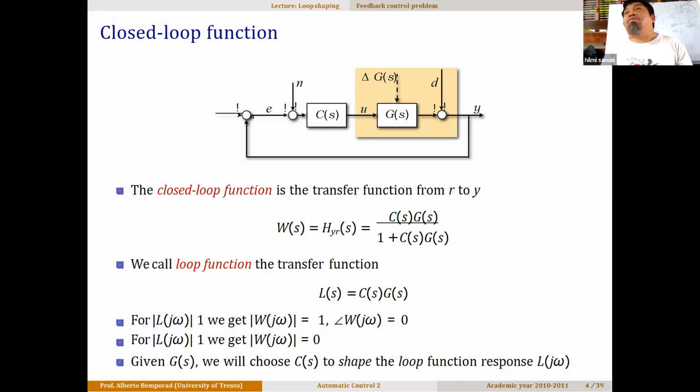So in the frequency domain, we talk a lot about energy. When we bound the energy, the system will be stable. That's why, if you still remember in your Circuit Theory 2, Signals and Systems, Parseval's theorem, if the system is stable, bounded input, bounded output. We are talking about the energy. Bounded input energy, we will have a bounded output energy. So if you have bounded input, bounded output, the system is stable. And that is what we want. And that's what we are doing.